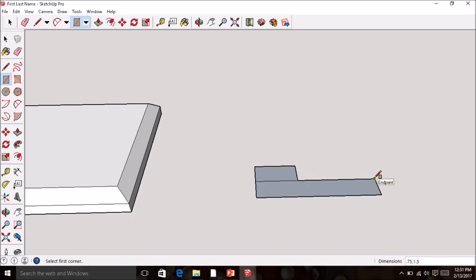I'm going to come back to this corner, and we're going to type 1.5, comma, 0.75, going off to the left, and hit enter. And so we end up with 2 rectangles behind this rectangle, and they should be pretty even, and I should have my midpoint right there in the middle, which I do. Now I have to do the exact same thing that I just did off of this endpoint.